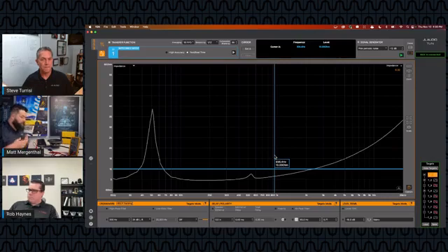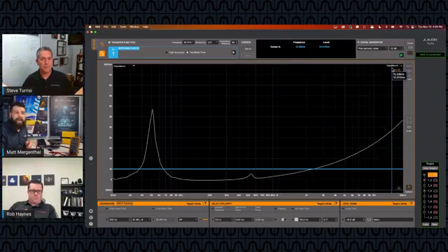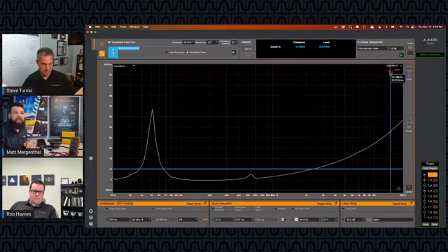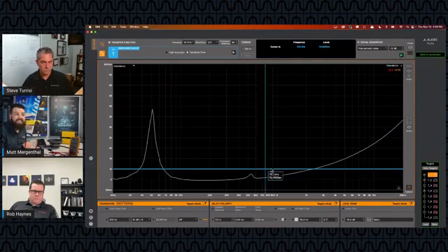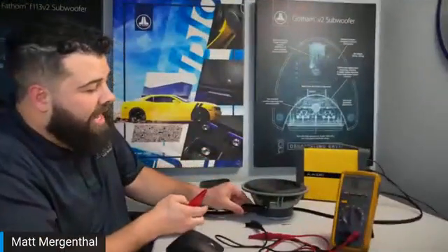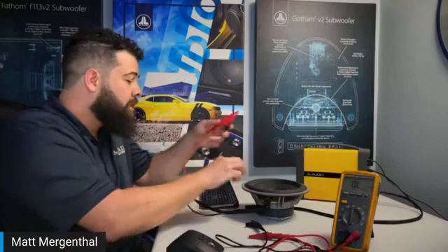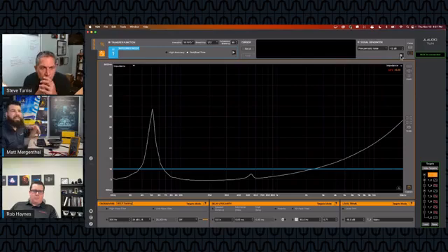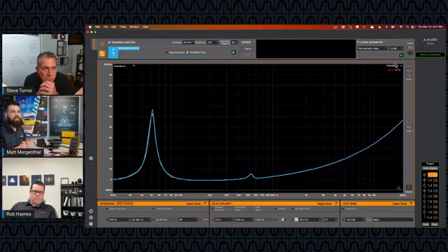Perfect. So moving on from here. Now that we've calibrated it, I'm going to go back up to the top right corner in the input combo box, and I'll right click and select set calibration. Now you'll notice the value actually went to 0, but on the graph, you can see it says CALD, like calibrated. So now we know that our measured data is calibrated. So I could then pause the signal generator, and I'm going to go back to measuring the speaker again, and let's see what changed. The change that we made was very little, not a large change by any means, but we'll be able to see how it changed with the calibration versus no calibration.